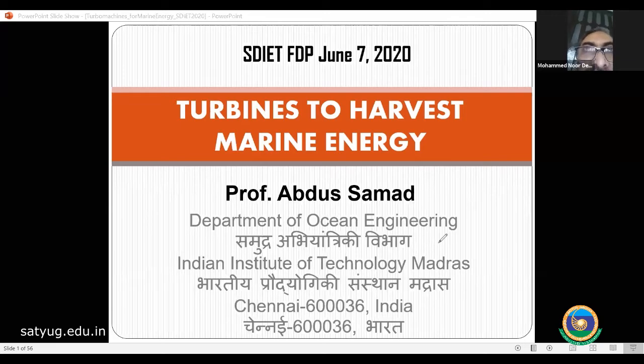My father was also from the hydraulics background, so I learned from him that dikes were being made to store the water during the high tides, and turbines were used, specific turbines, because it was a low head situation. So the bulb turbines were being used. They are basically axial flow turbines, very efficient ones.